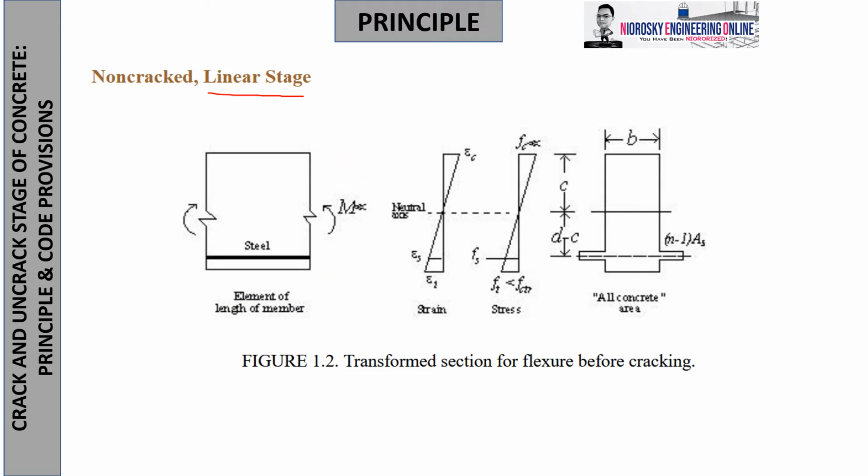So therefore, there can be some allotment that we may consider the entire concrete itself. So by that sense, if you have some reinforcement installed, then we would like to deduct the equivalent area that is being displaced by the steel. So that's why it becomes (n - 1) times As. If you are to be strict in calculating the performance of concrete, assuming, let's say, there is a hole here, and then I'll try to insert this reinforcement.